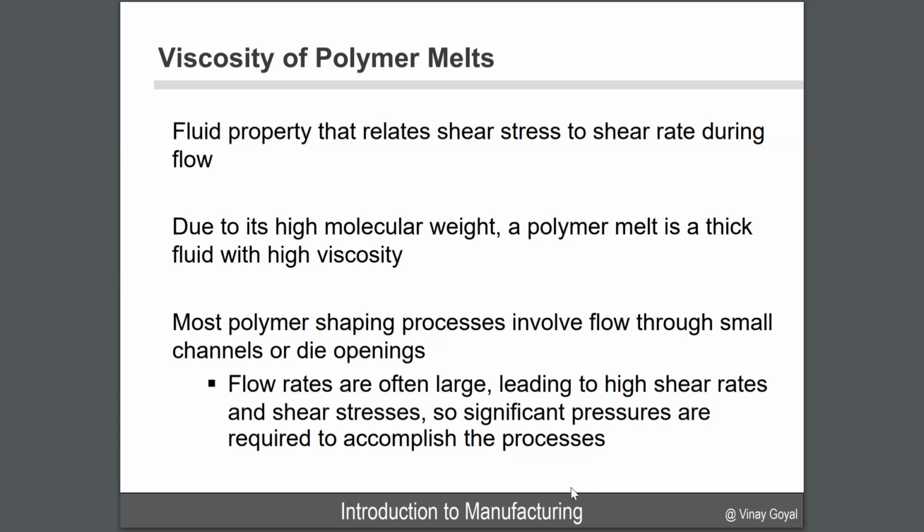Due to the high molecular weight, a polymer melt tends to be quite thick in consistency. It will have high viscosity. So therefore, most polymer shape processes involve flow through a small channel or die opening. I'll show you some examples with images. These flow rates often need to be large, because you want high shear rates and high shear stresses,